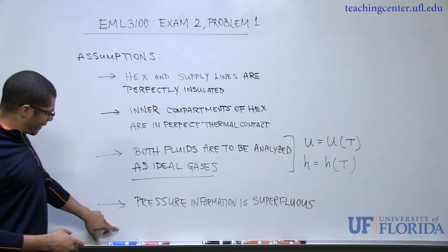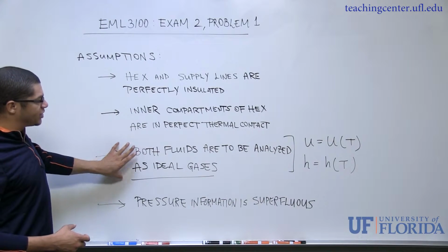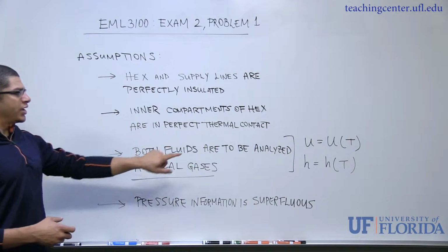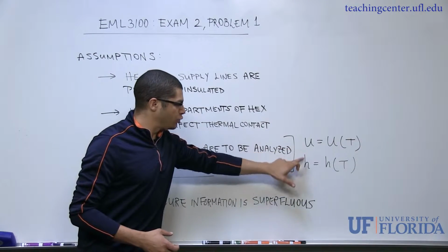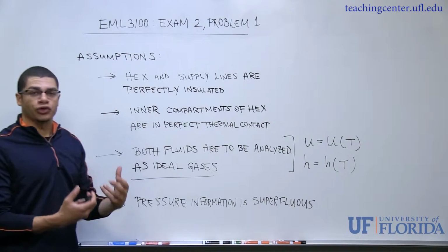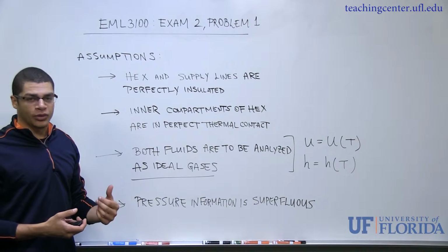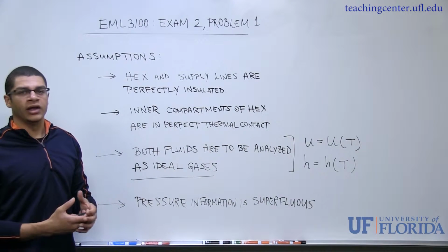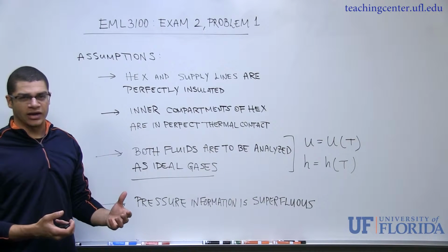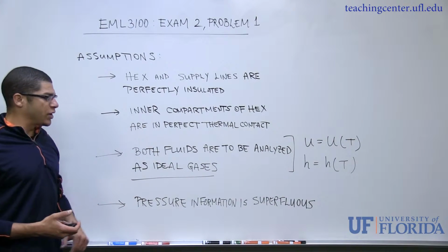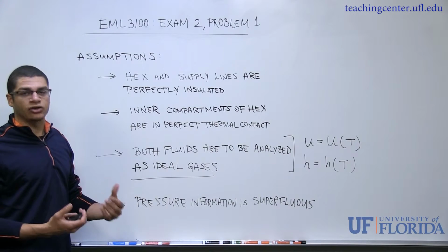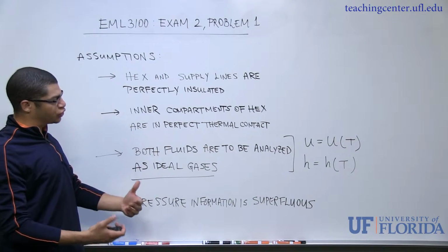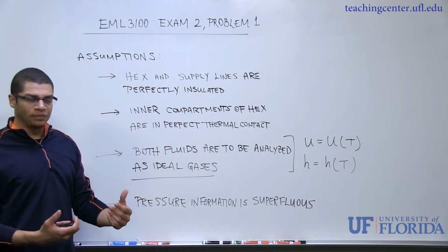And finally, because we're analyzing the fluids as ideal gases, and I've listed on the side over here, you should remember or recall that both the internal energy and the enthalpy are functions of temperature only, and the pressure does not play a role if we conduct an ideal gas analysis. So the pressure information given in the problem is actually superfluous. It's just additional excess information to trip you up.